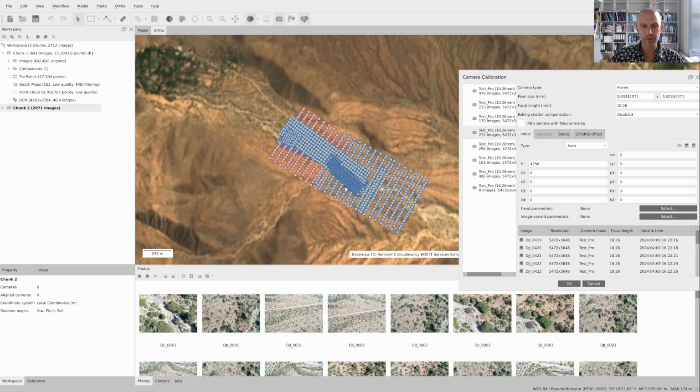So these three flights here were the large scale overview flights at the highest elevation, and then we put in a few additional flights at a medium elevation, and then flights more detailed at lower elevation, as you can see here. Again, the separation in the camera groups is not necessary, but it will help during the process of optimization, so I strongly suggest to do this.